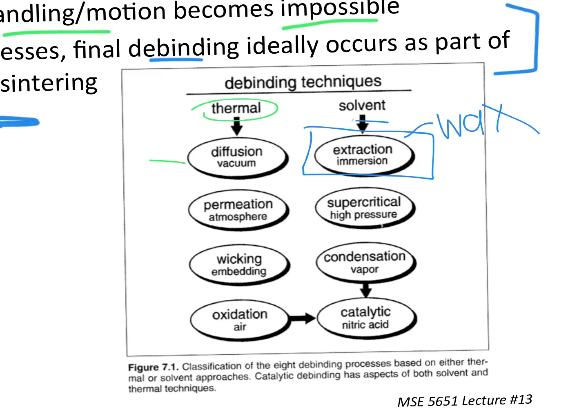High molecular weight, not soluble in heptane. All right, and so it does what it needs to do in terms of forming those bridges after all the waxy structure has been dissolved away. And it's only running at whatever it is, 50 C or something like that, relatively low temperatures. Okay, and there's also issues with stirring and circulation and so forth that can speed this up. But it is a relatively low cost technique, though it could be lengthy.